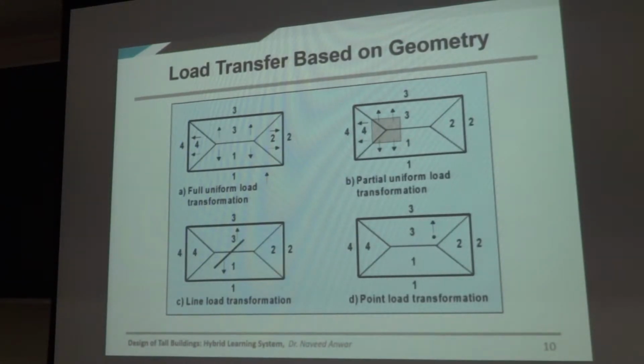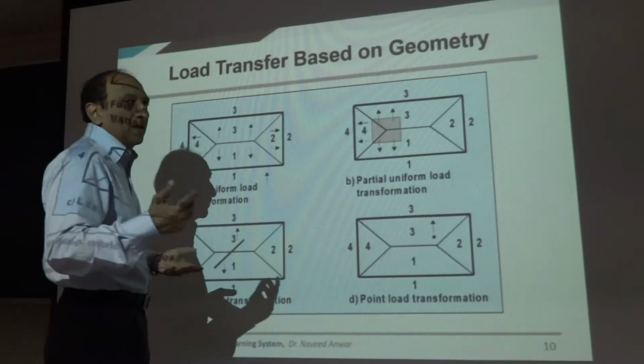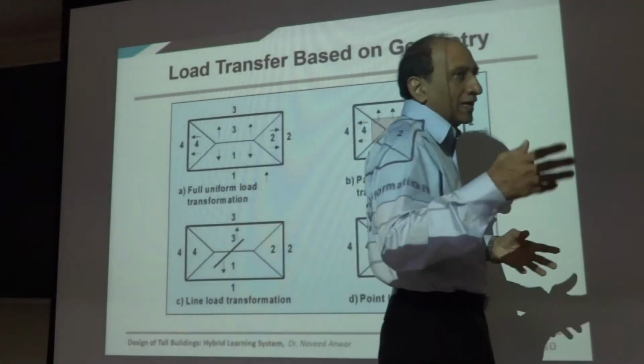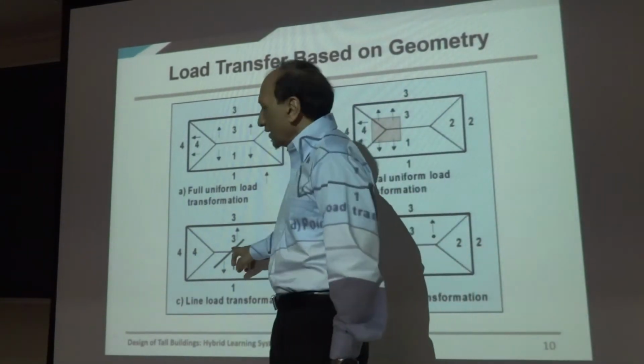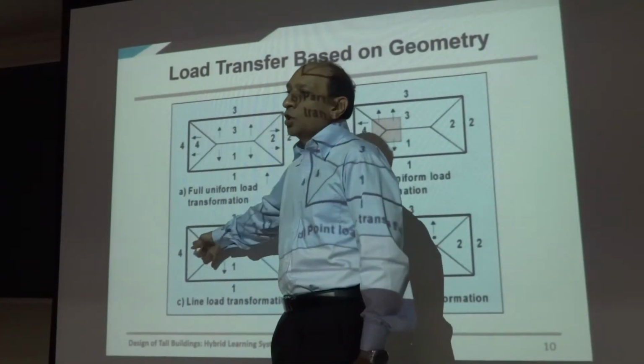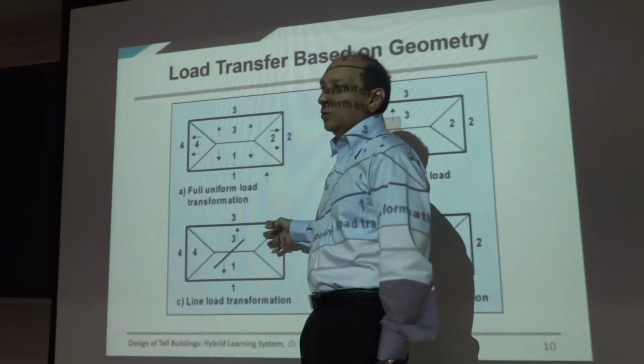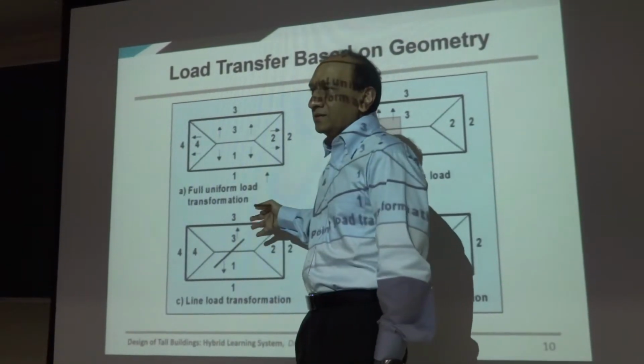So if you use a membrane for a slab, for example, and then you apply the load on it, the program will fall back on the old concept of the geometric load transfer because it has no stiffness information anymore, right? We try not to use that now, but previously we had little choice. So this is something based on the geometric load transfer that the programs will use. I do not recommend that you use that.